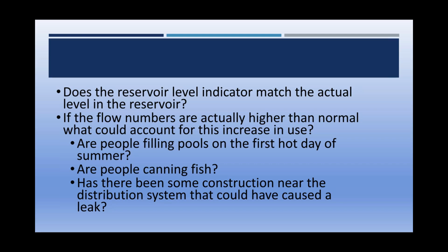So that was something that should have been caught when they buried the pipe. You never know. Once it's underground, you can't really see what's going on. And you have to rely on things like, in this case, the change between the static and dynamic pressure to figure out that there's a problem.